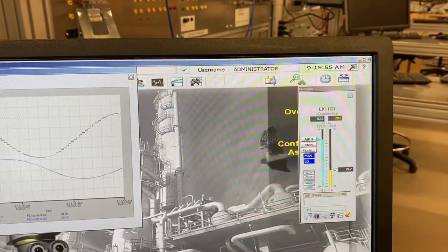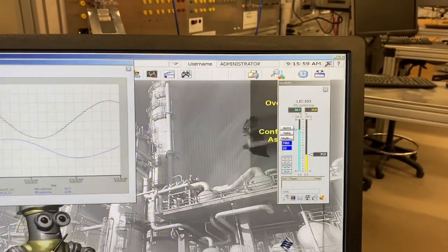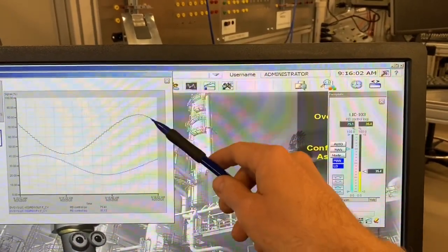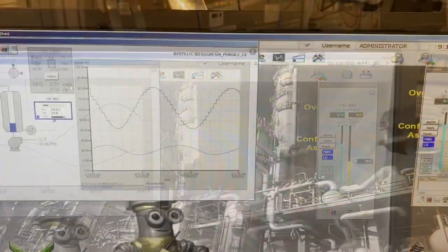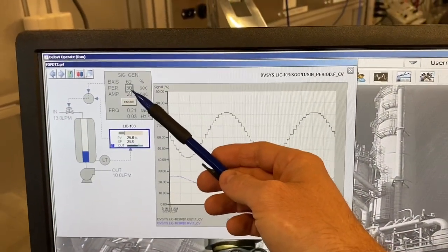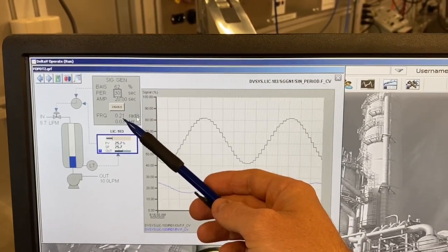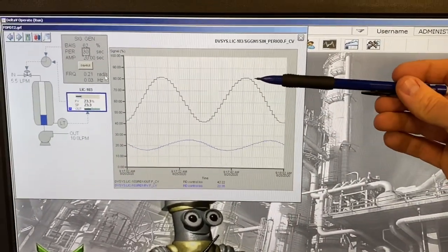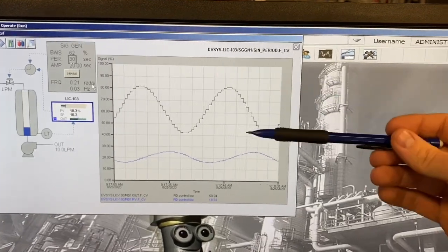So what we'll do now is calculate a different value for a higher frequency and see what that does to our gain, the change in input versus the change in output of our wave. All right, so I went and adjusted our period over here. I went from 60 to 30, and you can see our radian value, rads per second value, increased. What's still the same here is our amplitude. It's still at a total of 40 peak to peak.